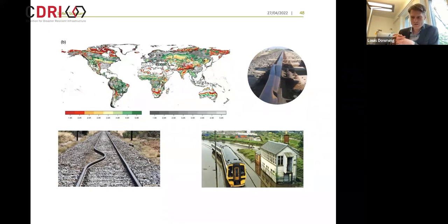But also, and this is something they did after the assessment, with this 700 meter by 30 meter new platform that they were building, they saw that with this new impermeable surface, they were increasing the flash flooding risk for downstream areas.